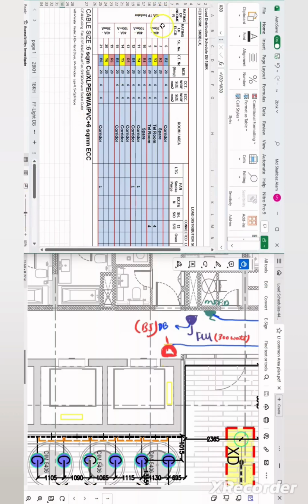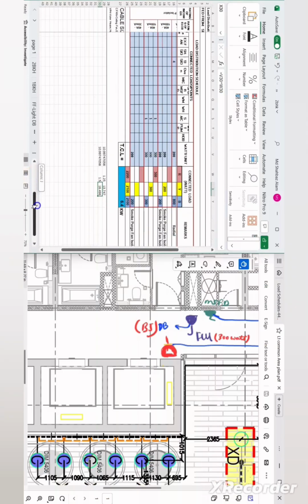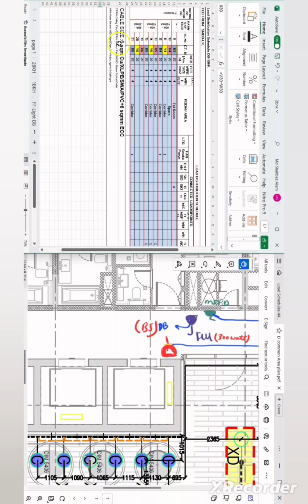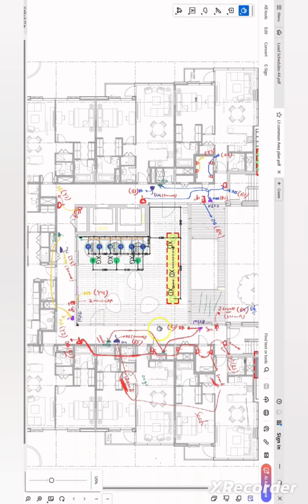But as the sub load have the ELCB rating as 40 ampere and the MCB rating is 20 ampere, so it is illogical to write here the main breaker rating less than the sub main breaker rating. So I match it and I wrote it 40 ampere triple pole isolator. Okay, the cable size for this 6.4 kilowatt is 4 square mm wire is also enough, but I wrote 6 square mm wire with considering all safety factors. Hope you are clear with this topic, that how to distribute the power load in the common area and how to do the circuit formation for the power load in the common area.